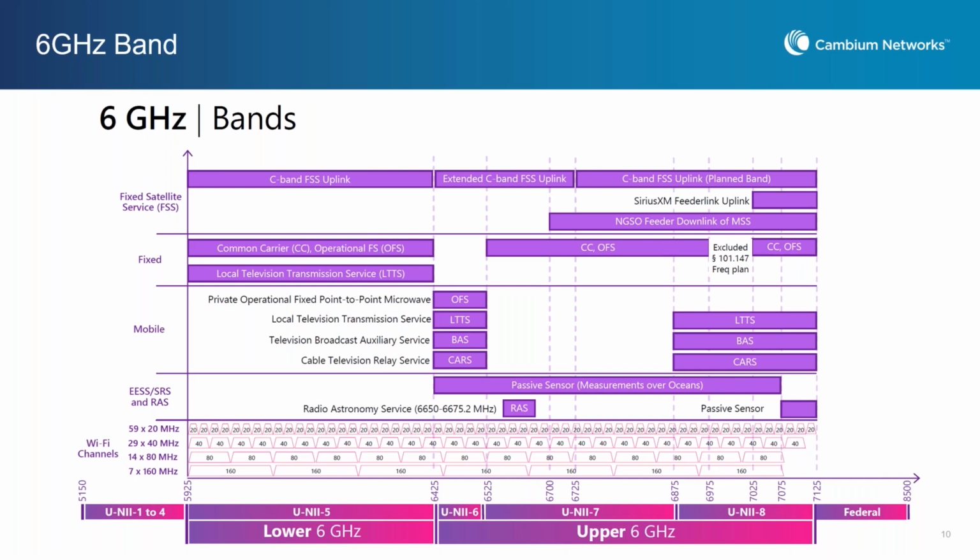There are going to be more like this in the future. But the concept of being able to coexist next to microwave backhauls and avoiding them is where AFC comes in. There are algorithms that run on the radios themselves that coordinate with the database of microwave entities. The fundamental goal is to avoid interfering with the mission critical microwave products.